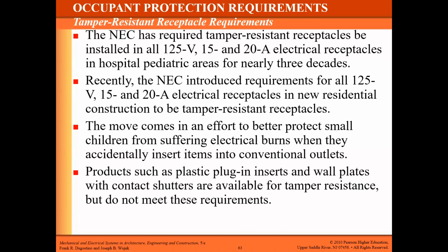But the idea is to keep kids from hurting themselves, because kids are notoriously curious, and when they see something shaped a certain way, they think, oh, well, that's going to fit right there. It would be really easy on an older style non-tamper resistant receptacle to electrocute yourself by just poking a little piece of metal into one of those slots. So these things have been required in certain circumstances, but these are getting more and more prevalent in residential applications now.